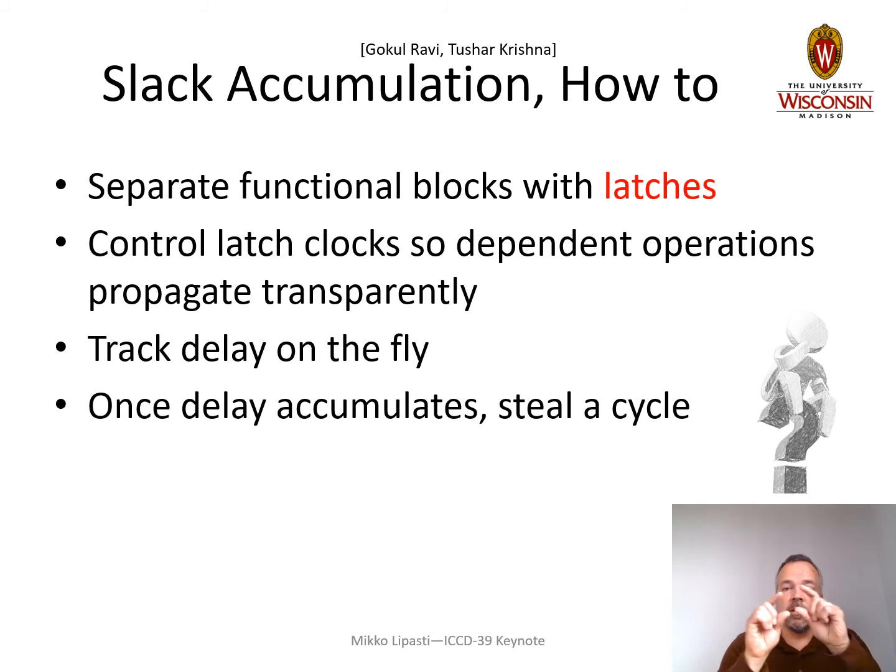And then build a simple little counter circuit that sits next to it that understands the behavior of these instructions with respect to how much slack they may or may not have. And this simple adder-based logic just accumulates the delay on the fly and keeps track of it. And once the accumulated delay reaches an entire cycle, then you basically steal a cycle. You sort of clock things in one cycle early. And so you end up operating in a more or less synchronous fashion.